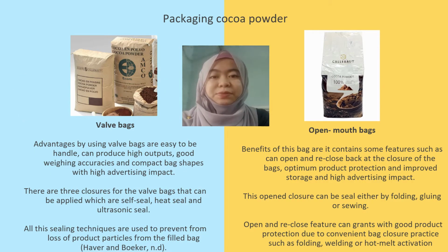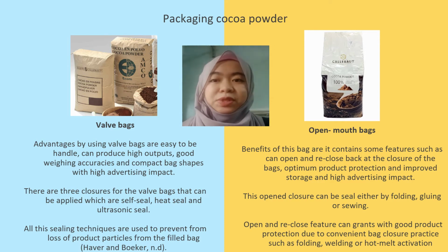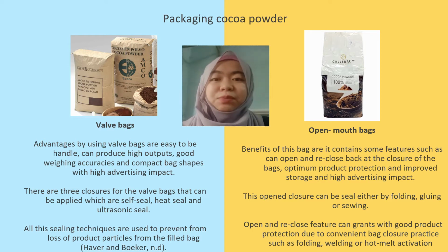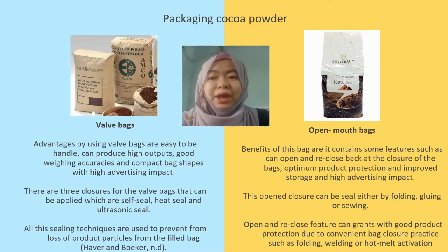I'm going to the last part of the factory information, which is the packaging of cocoa powder. The packaging of cocoa powder is divided into two types, which are valve bags and open mouth bags. First, I'm going to explain more about the valve bags. The advantages of using valve bags are that they are easy to handle, can produce high outputs, have good working accuracy, and have compact bag shapes with high advertising impact.